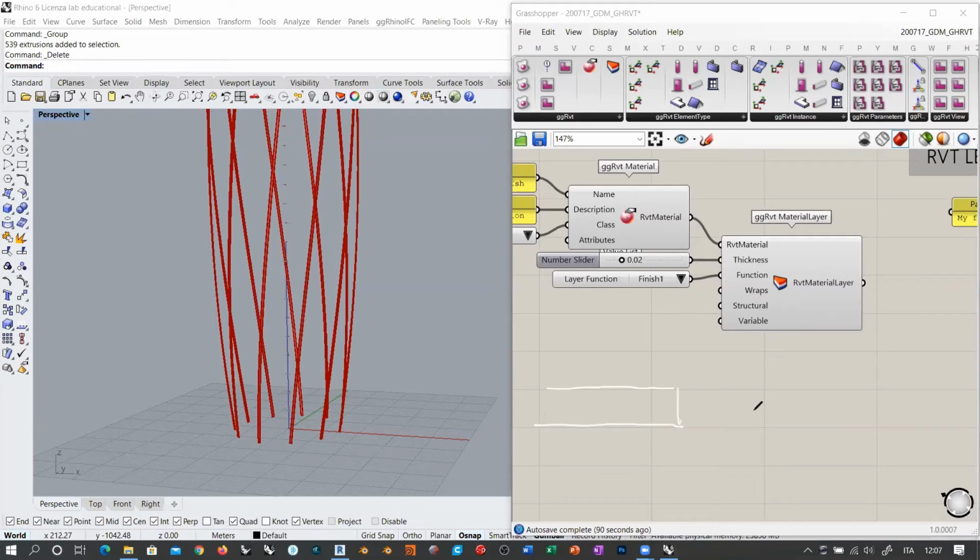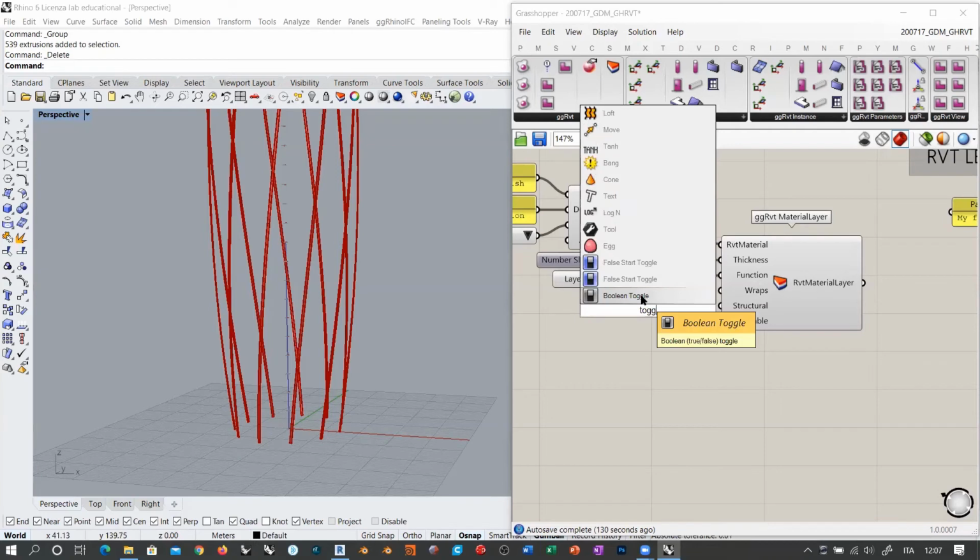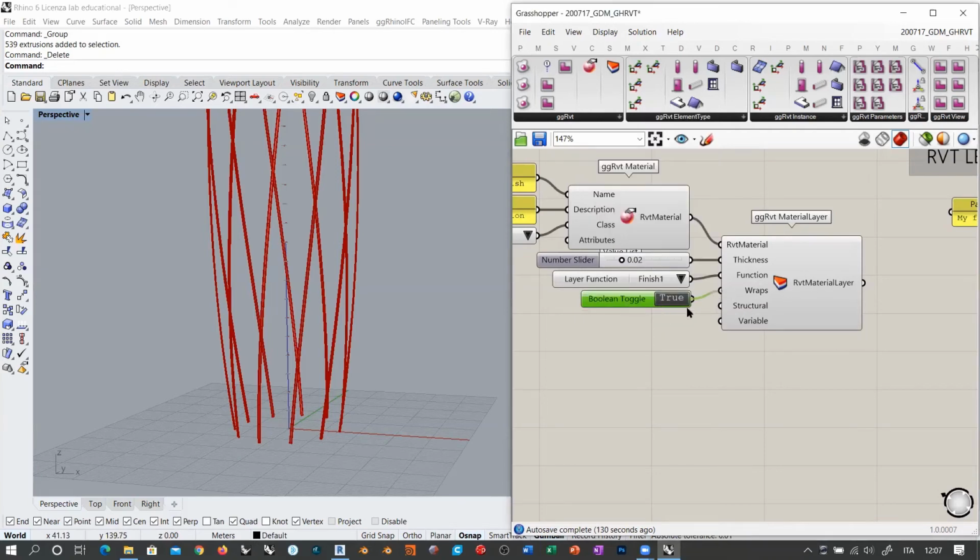like this, and it ends like this. So there is, for example, some railing here, some balcony somehow. Then there will be the finish layer here. If you say that it wraps, it means that it can turn around the corner and also complete this finish here. So this is something that you might want to turn on or off, depending on what particular situation you are facing. But by default, it's set to true. So remember that this layer is capable of wrapping around a corner.